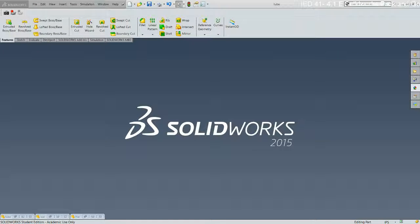Welcome to Introduction to Engineering Design, and today we're going to deal with some more mates, combining parts in an assembly. So what I've got is three pieces open here. Down in my lower left-hand corner, you'll see I've got a tube, a rod, and a flat. What I'm going to do is make a new assembly, and I'll do it from this little paper tab looking thing, and it's going to say make an assembly from a part.